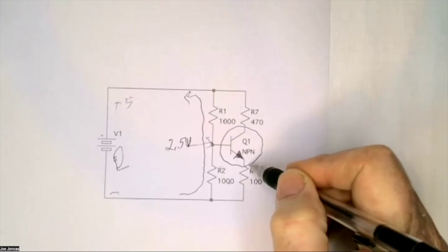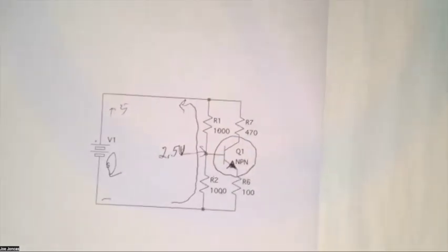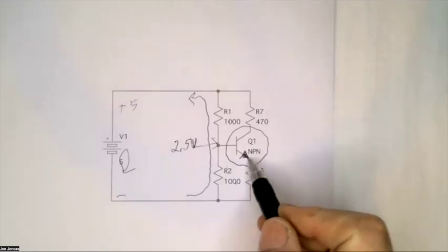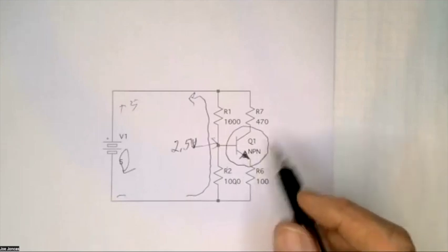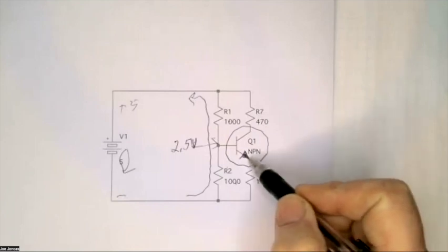It's pointing away. Darren, you had a term for that to help you remember it. Not pointing in, NPN. So the arrow is pointing out, so it's not pointing in. That makes it NPN. If it's pointing in, then it's PNP. But this is a junction indicated by this.